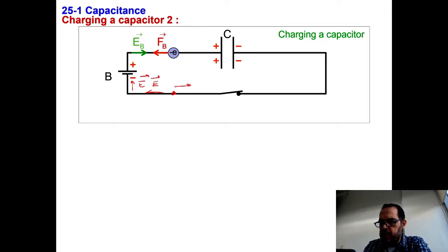So the electron will be experiencing a force in the opposite direction, so the electrons will flow towards the other side, the negative side of the capacitor. So we have accumulation of positive charges in this plate and accumulation of negative charges on this plate. This will continue, but remember, these positive charges are going to generate themselves an electric field in this direction. Hence they will start again attracting the free electrons. So this will continue until the forces on the electrons cancel each other.